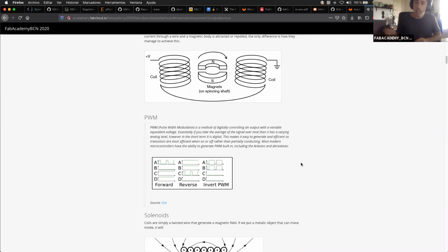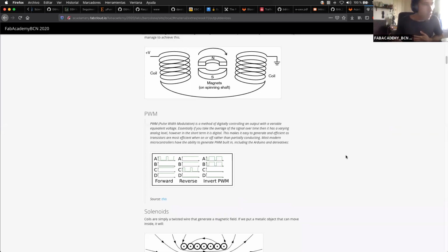After you overcome the inertia, the current goes down and you get to what we know as the running current, which is the current that the motor needs to run at normal speed without any load. This totally makes sense with the previous part, because when you have more current, you have a stronger magnetic field, and the stronger the magnetic field, the more torque you can develop in the motor and overcome the inertia it has when it's stopped and has to accelerate. Does that answer your question, Pablo?